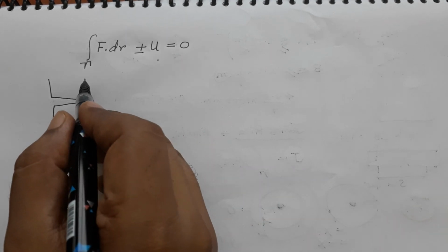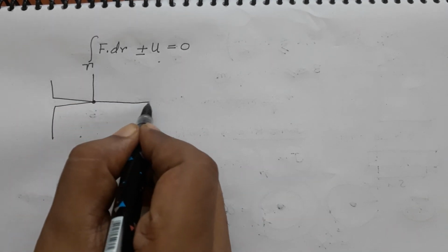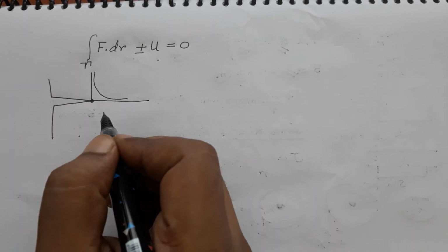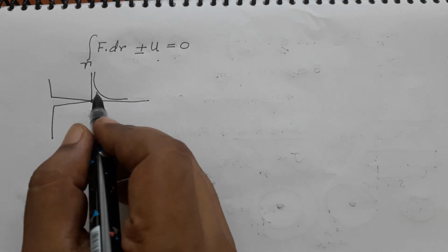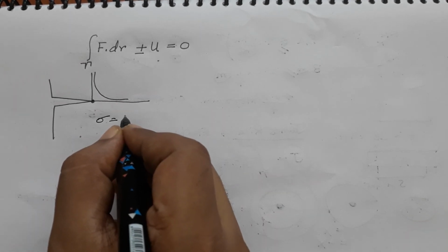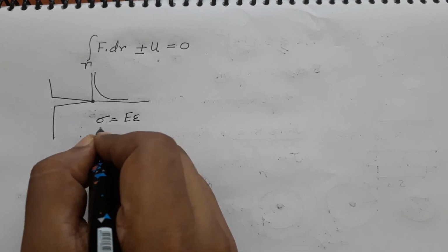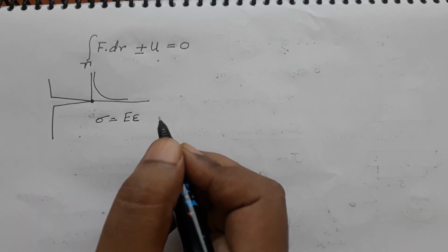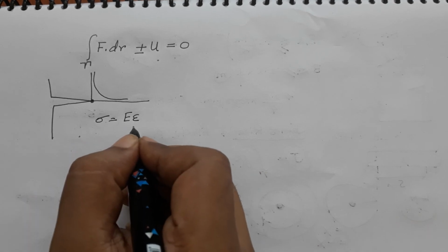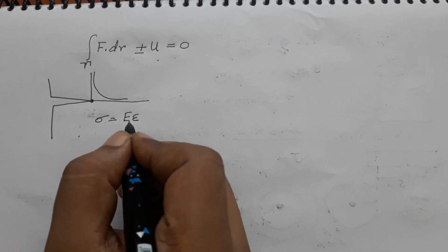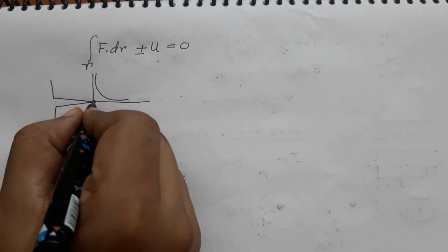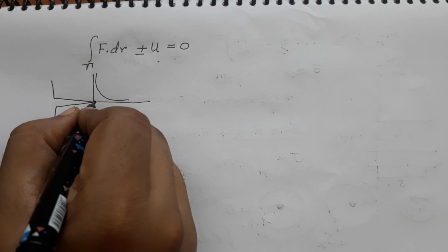So, according to the theory of elasticity, the stresses are infinite, and so will be the strains, because in linear elasticity you will be following Hooke's law. So, stress will be related linearly to the strain, and if the stresses are going infinite, strain must also go to infinity. But that does not happen in reality. What should happen in reality? We might have a different equation in plasticity, but even those equations will not be valid exactly at the crack tip.